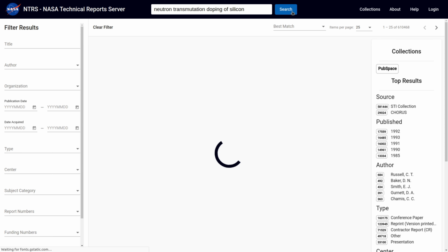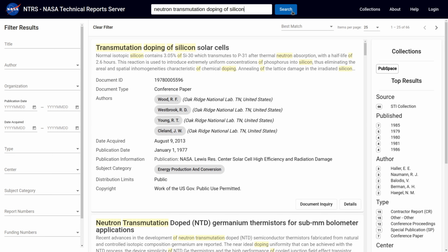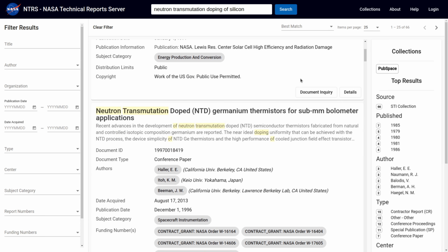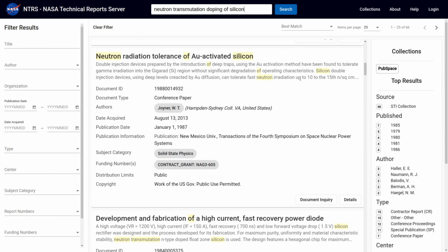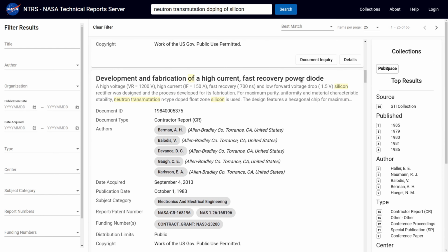Therefore, bombarding existing transistors in a chip with thermal neutrons is likely to change the transistor characteristics or cause them to stop working entirely. There is even an established industrial process that deliberately uses thermal neutrons as a method of doping silicon. This process is called neutron transmutation doping of silicon, and it's primarily used for applications that require a highly uniform doping concentration that cannot be achieved by other means.